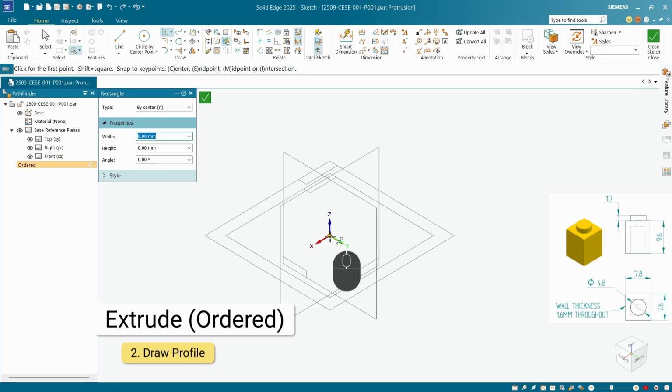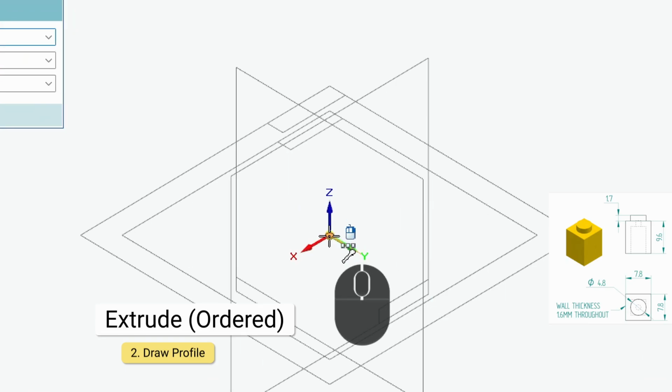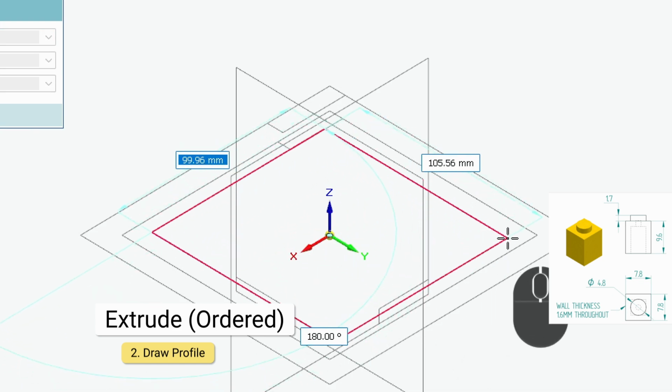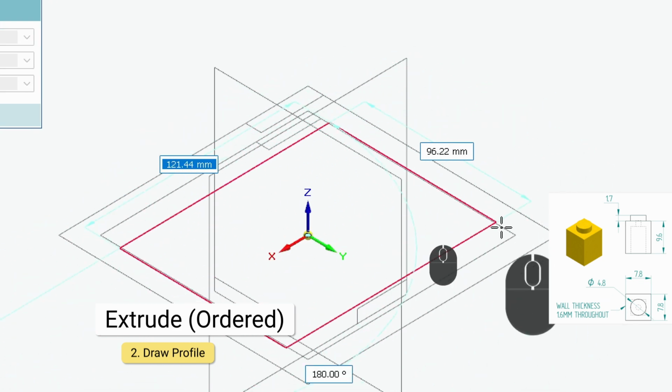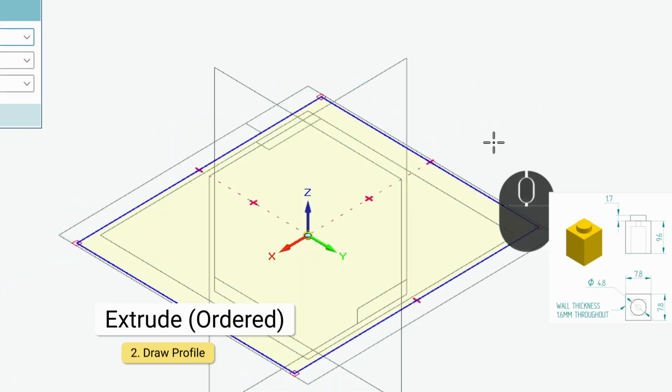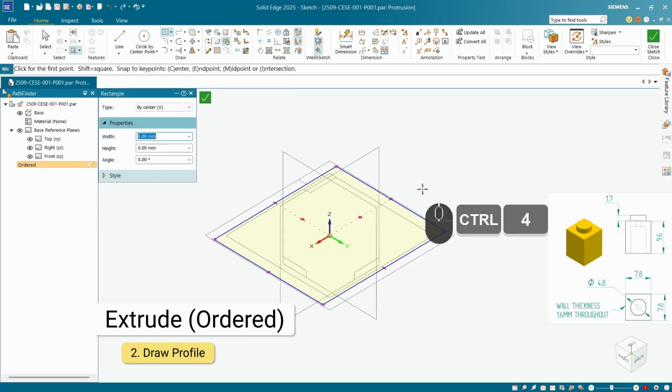And if I hover over the origin here, you can see the origin highlighted by the orange dot, I'm just going to click, and now that's the center point of our rectangle. I'm not going to worry too much about the actual dimensions. I'm just going to click anywhere. And that's the basis for our sketch.